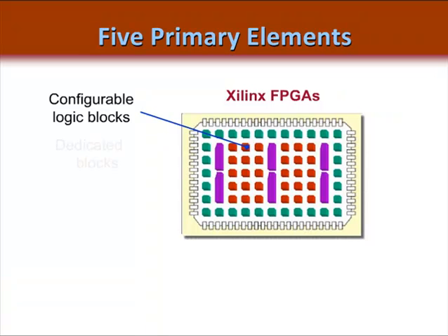Throughout the FPGA are columns of block RAM, DSP slices, and other dedicated hardware. This includes PCI cores, eMAC blocks, perhaps a PowerPC processor, and other dedicated resources. Since the type and quantity of dedicated hardware will vary by product family and density, it is a good idea for you to flip through the datasheet to help you decide which device family is right for your application.